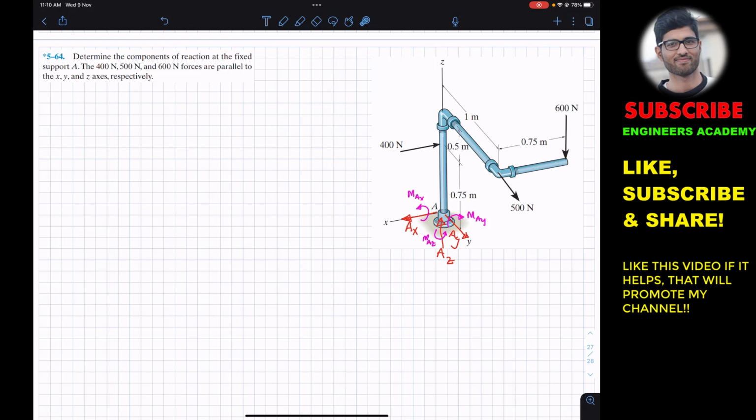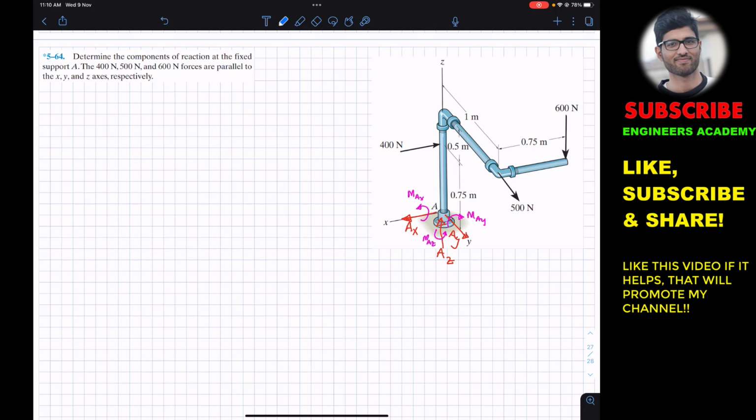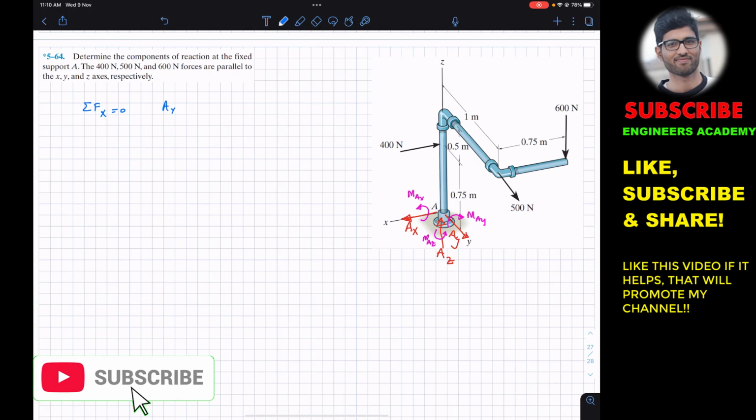Since this whole mechanism is in equilibrium, we can apply the equilibrium conditions. The first condition is that the summation of forces along the X-axis must be equal to 0. In the X direction, we have this 400 Newton force and this AX. AX is in the positive X and 400 Newton is in the negative X. This one is along Y and this one is along Z. So the summation of forces along X gives AX minus 400 equals 0. So AX is equal to 400 Newtons.